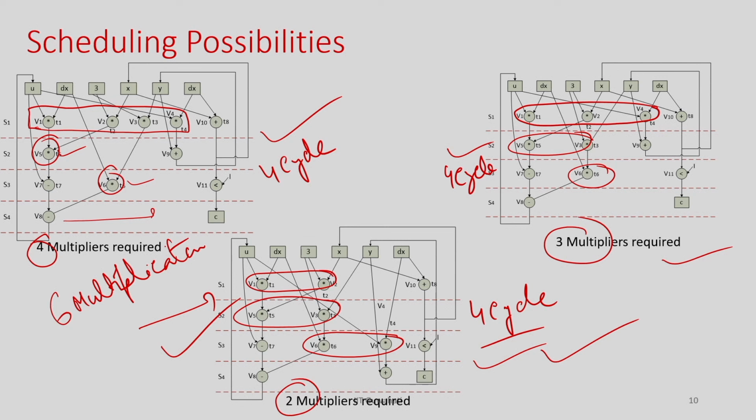I can show you that in this particular example I can actually utilize 2 multipliers, because at most my requirement of multiplications in every state is 2. So, I need 2 multipliers, and I can put this into multiplier 1, this into multiplier 2, this into multiplier 1, this into multiplier 1, this into multiplier 2 and this multiplier. This will not create any problem. This is resource sharing, which is very important in the context of hardware, because I do not want to arbitrarily use a random number of hardware units, as that will increase my area, my power, my time, everything.